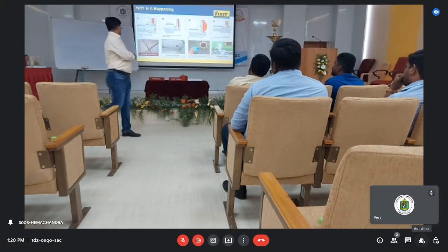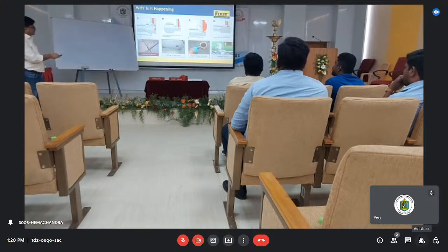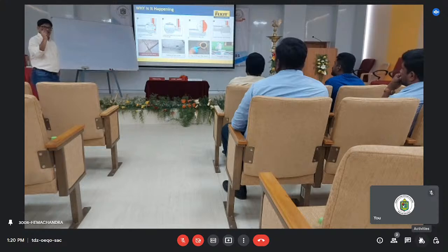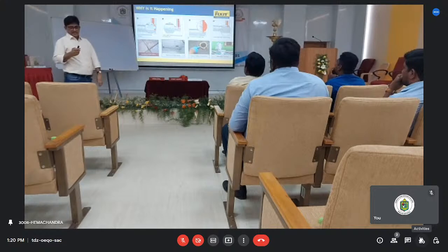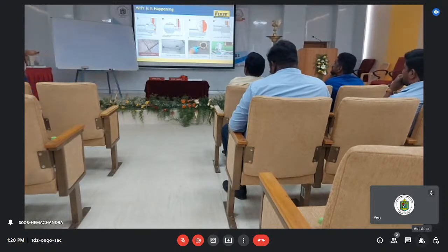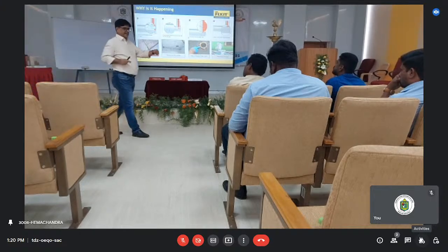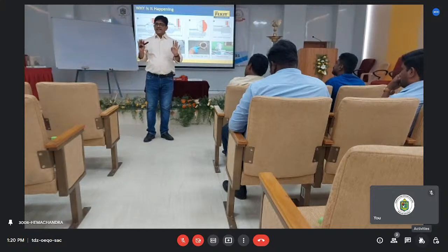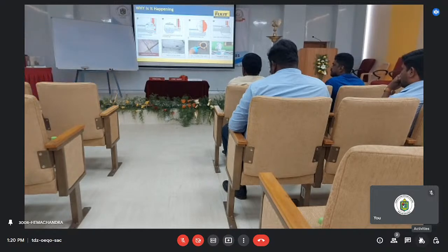So your areas are the cracks, the crack joints, the tile joints on the floor tiles, and also the cracks at the wall-floor intersection joint. These are the areas that have to be checked first. How is the condition of those? In most cases, your bathroom waterproofing can be easily solved if you do the tile joint fillings properly. 80% of the cases can be easily resolved. So that is the first thing.